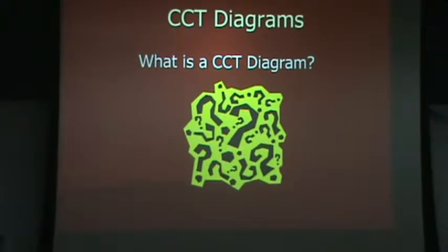All right. So I'll review slightly. Last week we talked about the equilibrium phase diagram, which gives us an idea of what phases we'll have present at various temperatures under equilibrium conditions. And we talked about how that wasn't really very applicable because we don't work in equilibrium most of the time. So then we brought in the TTT diagram. That gives us an idea of what kind of structures we would get under isothermal conditions. But even that, we don't really work in the isothermal world very often.